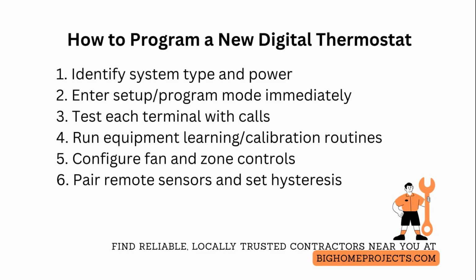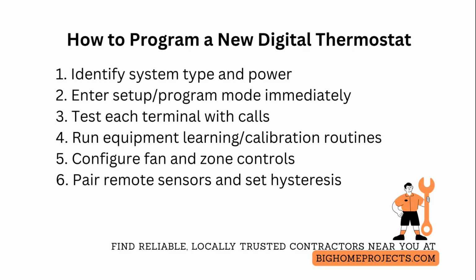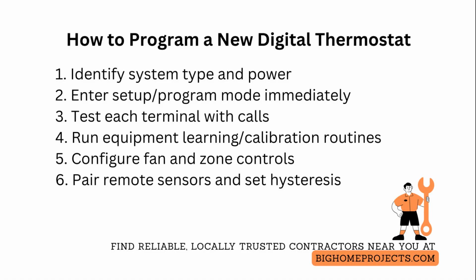Test each terminal by energizing the system. Call for heat and cool separately and watch for correct compressor, reversing valve, blower, and stage transitions. Listen for compressor start delays and watch for short cycling, which indicates miswiring or wrong system type selection.